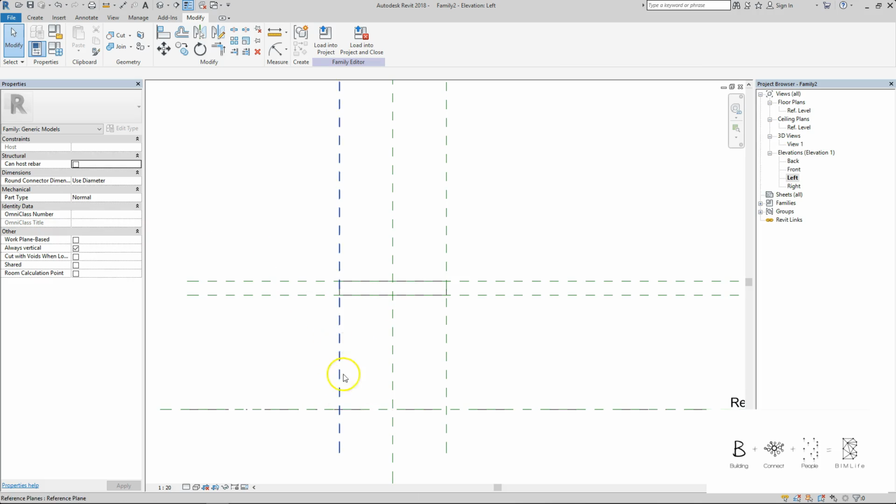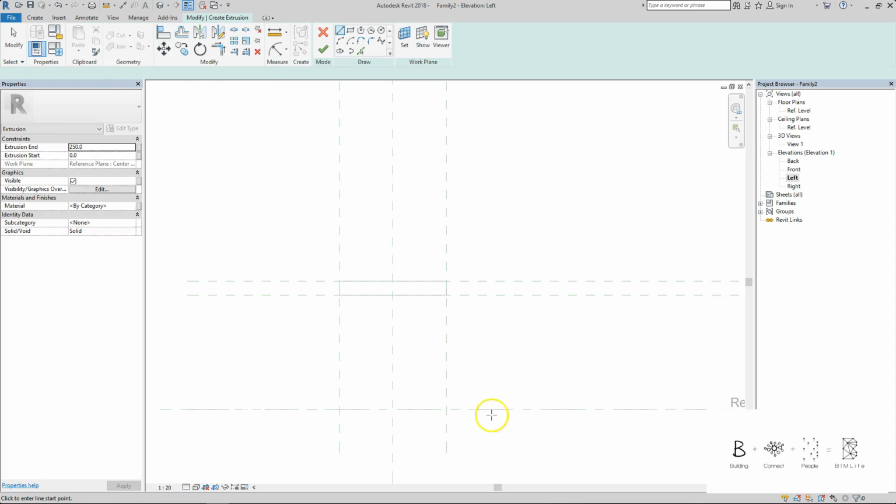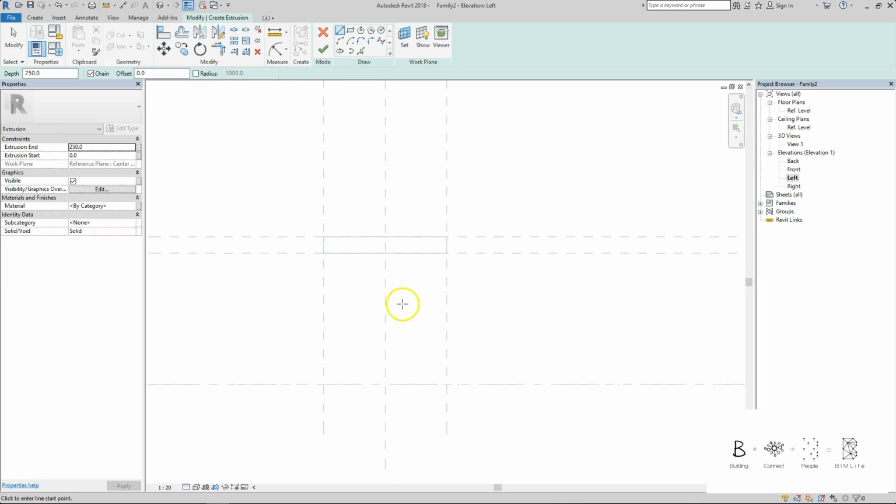You can start drawing the legs of the table using an extrusion, because there is actually no curved surface, so we can use a basic extrusion. And just to check the dimensions a little bit, okay, let me see, it's 100, and so it's 50 away from the sides. So this will be 50, and I'm probably going to do the measurement later. I'll just draw the outlines of the table.